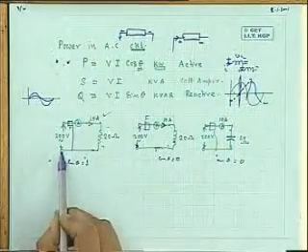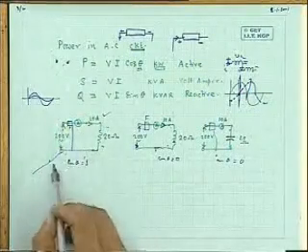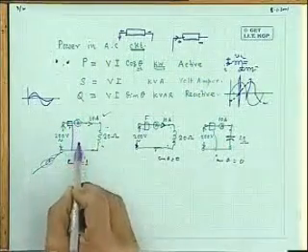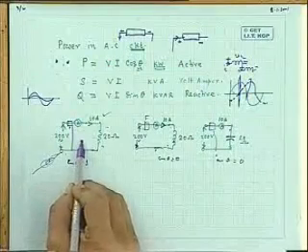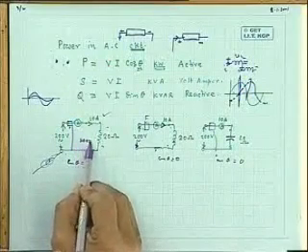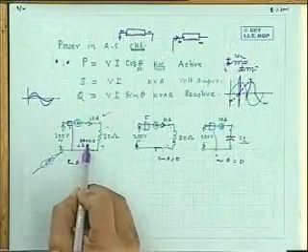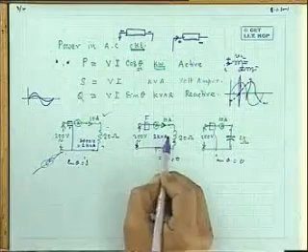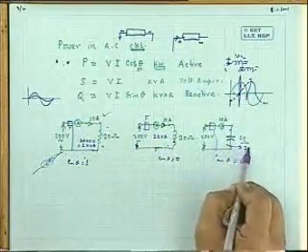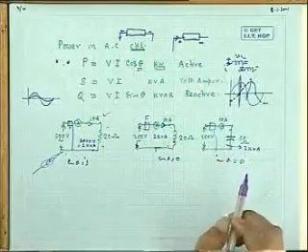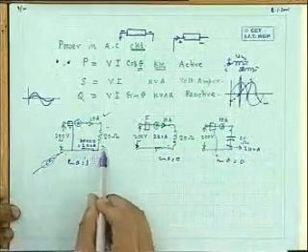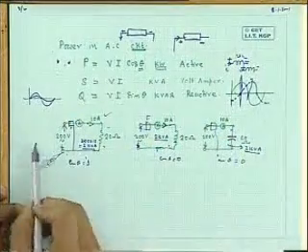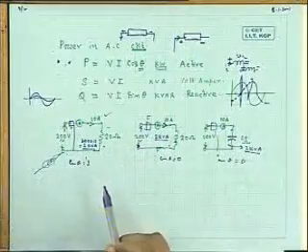So far so good. It appears okay, logical. But there is a problem. The problem is with your supply authority. Before I go to that, what is the volt ampere rating of this circuit? It is 200 into 10, that is 2 kVA. The volt ampere rating of this circuit I will also call 2 kVA. This is also 2 kVA. All the consumers are rated at 2 kVA.